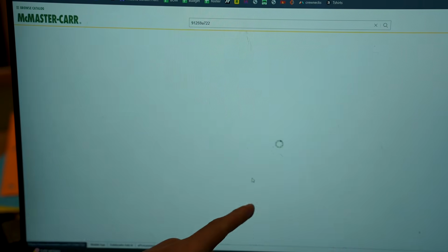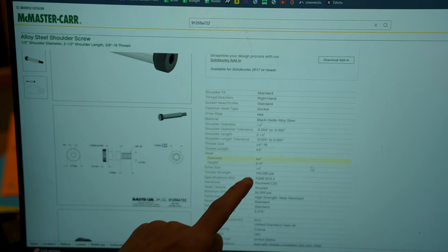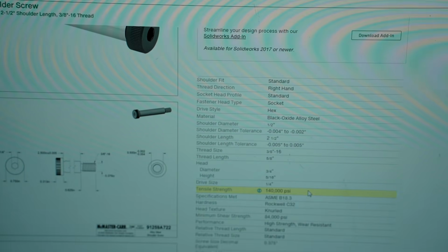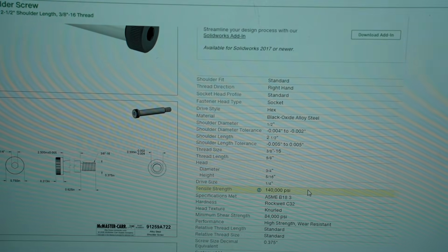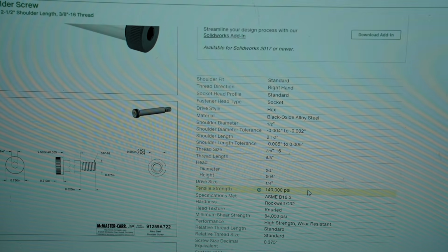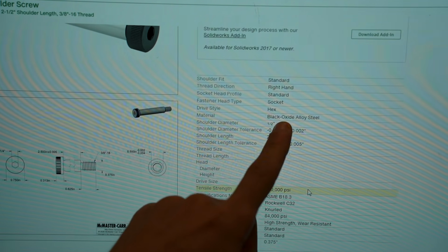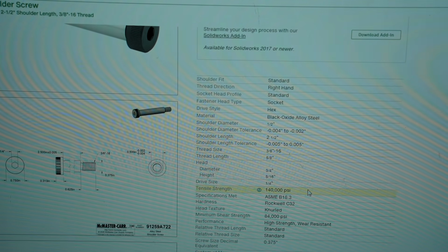And we pull up a list of parts, then we can check the product detail, and we're going to get 140 KSI. How reasonable. How lovely from McMaster. That is very strong for steel. Mild steel usually does end up in the 80 KSI range. So maybe it's a different formulation. It might be stainless. What do they say? Black oxide. Alloy steel. It's an alloy, as opposed to all the other steel out here. So who knows? I guess it's an industry secret.